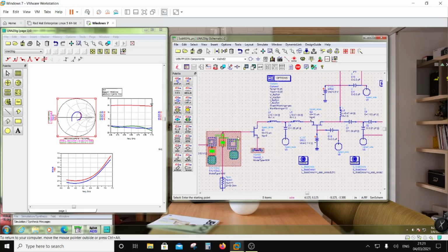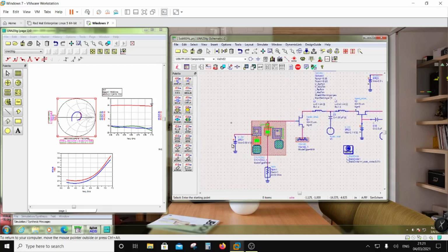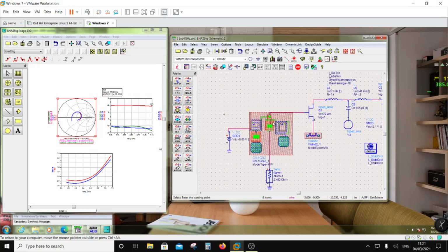Then there was a scope of improvement on the transistors and matching. But here NF-min and NF2 are almost the same, right? So then the contribution to noise figure is mostly coming from the loss in the input stage. It is not with the biasing or the tuning, right? Because NF-min and NF2 noise figure is the same, right?